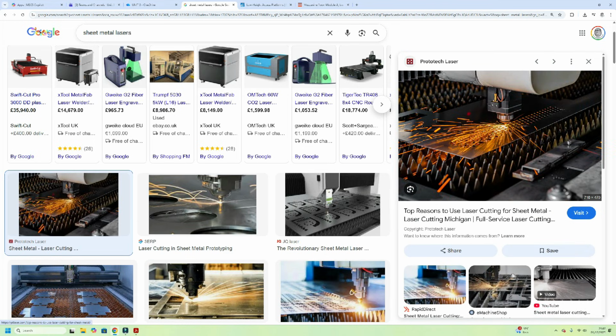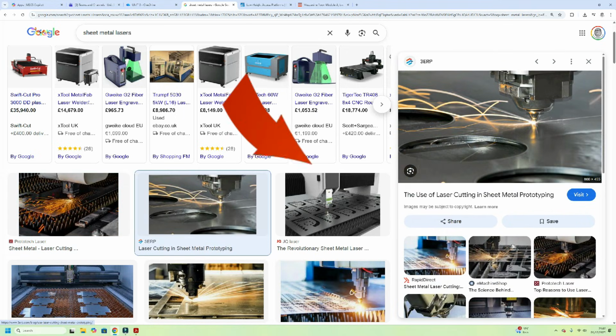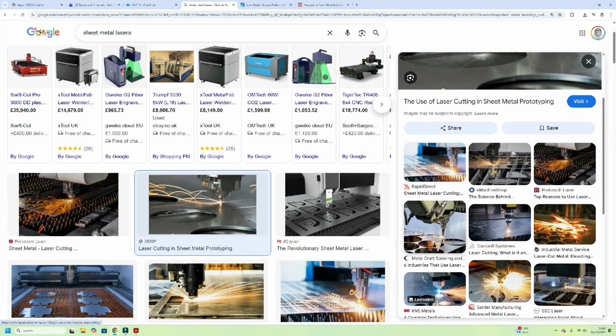Now laser cutting is really fast. Nice clean edges. If you look at that, nice clean edges, hardly any dross underneath, and so on. And I think the biggest sheet they can put on, according to one of my old students, is either a 3 or 4 meter wide sheet by 6 to 8 meters long, and you can get many parts. For the software, you use a DXF file of the profile they want to use.